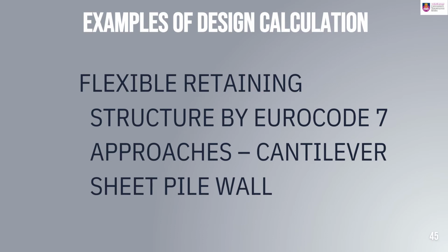For equilibrium, the active pressure on the back of the wall must be balanced by the passive pressure both in front of and behind the wall. If an arbitrary point C is chosen and it is assumed that the wall will rotate outward about this point, the theoretical pressure distribution on the wall is as given previously. The toe of the wall is deep enough such that the conditions that prevail are known as fixed earth conditions.